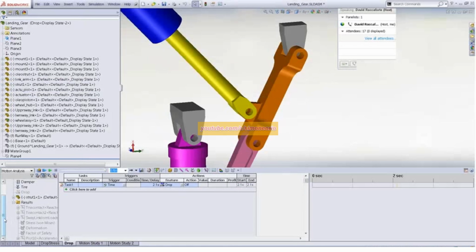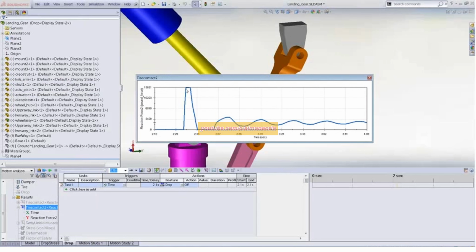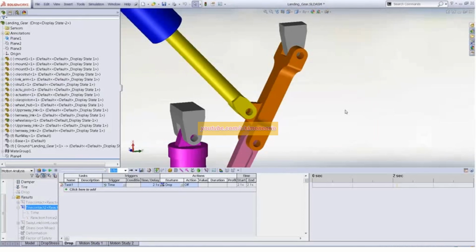And how did I pick my time step? Well, I looked at my contact forces and chose the highest forces, and that's the time step that I exported. We can also export multiple time steps. So we'll open this part,